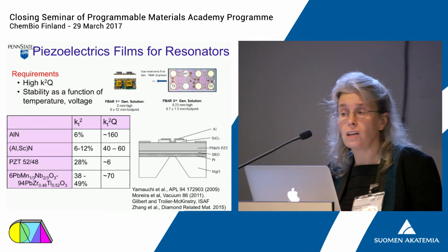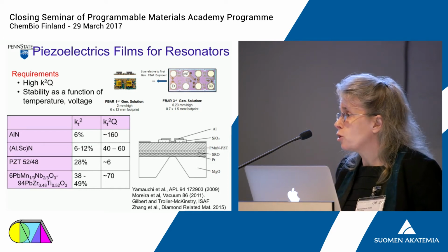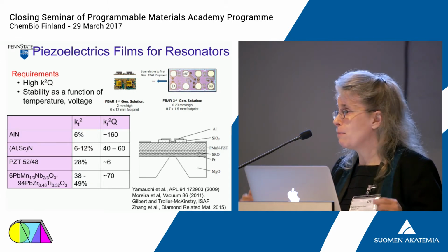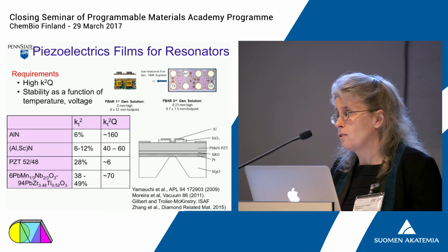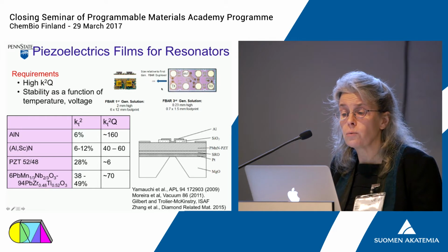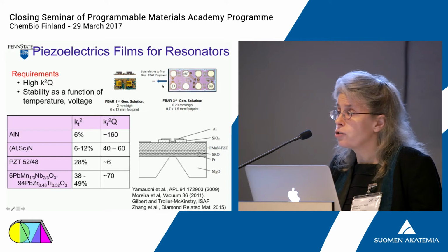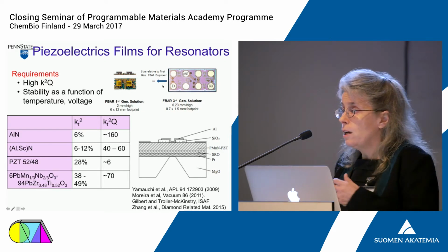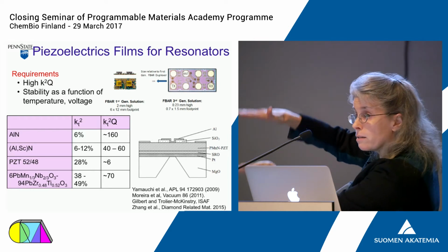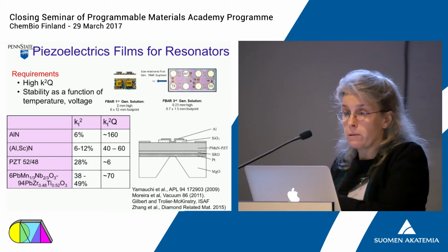Out of a nice high-density ceramic, you need at least one of those for every frequency band on which you're going to operate. And so modern cell phones have at least 6 frequency bands in them. There was a tremendous incentive to reduce the size and weight of that component. And the approach that was taken was to utilize an aluminum nitride thin film. Aluminum nitride thin films are piezoelectric, and as I apply an electric field in the thickness, I will generate an oscillation that corresponds to the frequency of the cellular communications.